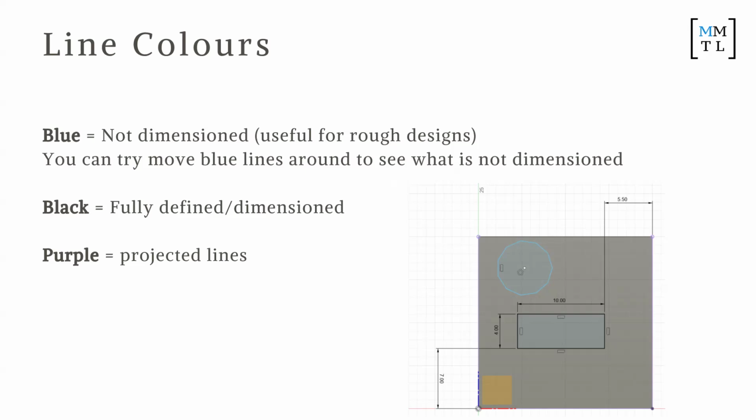And it should be shaded blue. If, for example, you create a closed sketch, like a rectangle or circle, and you expect it to be closed, it should be shaded blue. If it's not shaded blue, it means that you missed a point somewhere, and you're going to try to do 3D stuff and it's not going to work. So make sure that if you expect a closed profile, it's shaded blue.